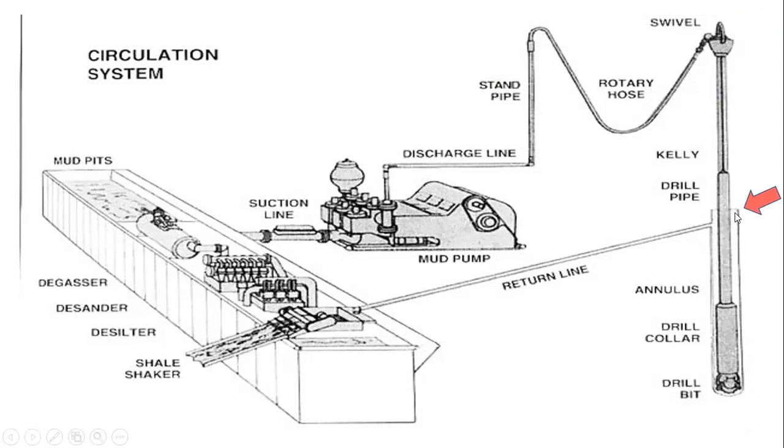Now, this is the beginning of your wellbore. Your wellbore is like a hole, okay? And then this is the top of it. So when it goes in, the drill mud is circulated through the drill string into the wellbore, and it gets to this place where we call the drill bit.